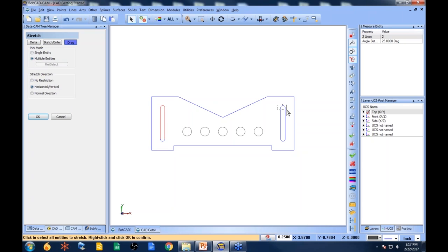This is where you have some geometry and you want to change the width of the slots. Maybe you want to change this cutout. You can pull this in different directions. So it allows you to modify your geometry, stretching the geometry without having to do line parallel and then trim it. So stretch is actually a really useful feature that's been added to the software in the last couple of versions. Okay, you 29 guys, you're lucky because it all comes with it right out of the box.